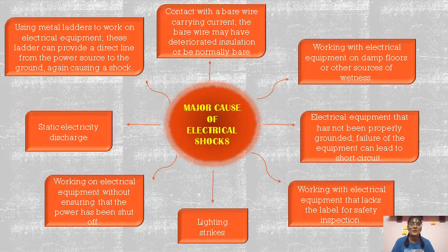The last major cause of electric shock will be using metal ladders to work on electrical equipment. These ladders can provide a direct line from the power source to the ground, which again can cause a shock.